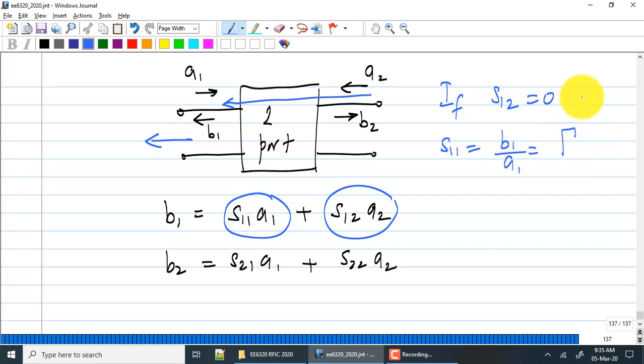The reason I'm explicitly pointing this out is because some people in common parlance nowadays call S11 the reflection coefficient, but it is true only in a specific condition. In most cases, if you're dealing with amplifiers, this would most probably be true. You want unilateral systems anyways, if you deal with active blocks. If you deal with passive blocks, it is clearly not true. That is just something to keep in mind.